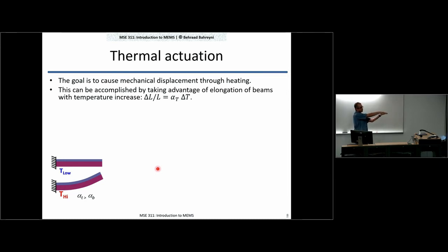If the temperature raised above a certain limit, it would just disconnect the circuit so that the temperature would go down again, and this was your control mechanism. You can do the same thing at micro scales. The issue is that the conductors that we have at these levels, the typical devices that we have for micro machine device systems, have thermal expansion coefficients that are fairly close to each other. Right? So you have silicon and some metals and polysilicon. They have more or less similar thermal expansion coefficients, so this is not going to be very effective.